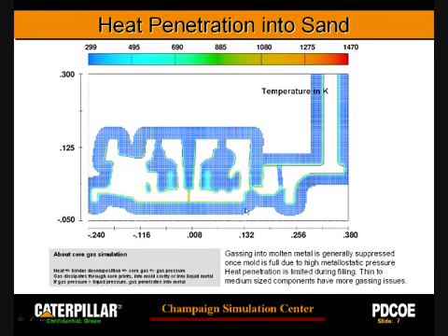If you have a lot of volume on the outside of the mold, even if you create the pressure, because the gas is compressible, if you have a lot of volume to contain it, you may not really have problems. What's causing problems is some of the cores which are thinner and intermediate size, which can be heated through quickly and create a lot of gas pressure, and they don't have a lot of volume to contain it.